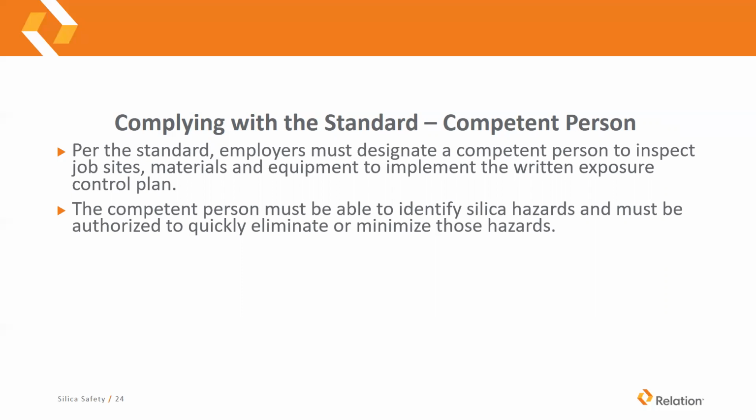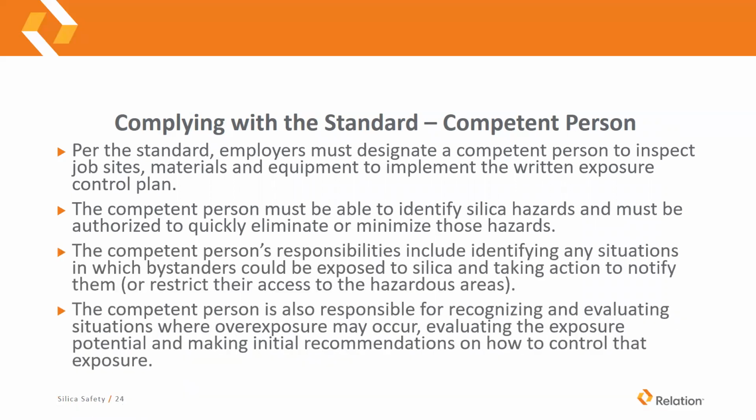The competent person must be able to identify silica hazards and must be authorized to quickly eliminate or minimize those hazards. The competent person's responsibilities include identifying any situations in which bystanders could be exposed to silica and taking action to notify them. So you also have to remember, when you're creating this silica dust, is the rest of the crew downwind from that? If they are, you need to either move them to a different location or